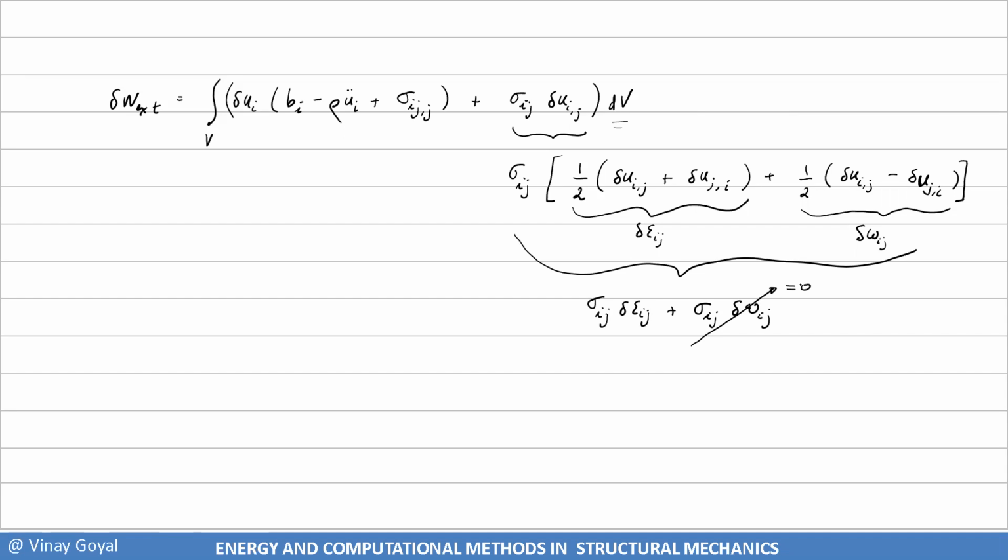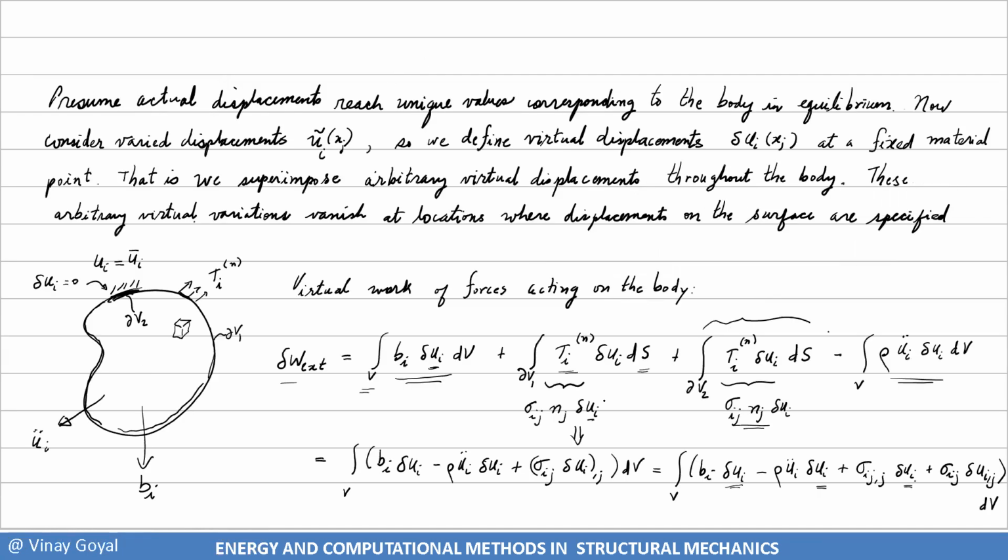But isn't this the equilibrium equations? They came out naturally here. You can see them. I didn't do any tricks. I didn't do any magic tricks. These are the equilibrium equations of elasticity. But I know that that's equal to zero, so I'll set it equal to zero for now, because I know it's zero. And what I've demonstrated is that the external virtual work, including the inertial effects, can be represented as